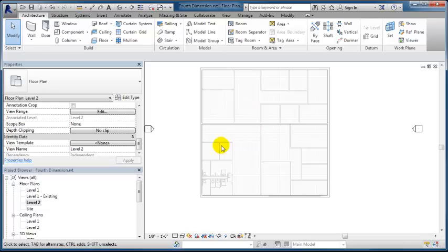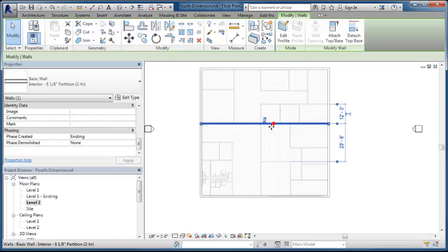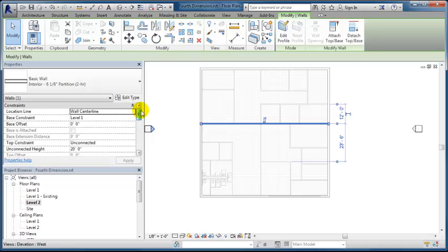All of the rest of the walls that are inside this area and this area are non-bearing walls. There are going to be all partition walls that go up 9 feet, and then our dropped ACT will be at 8 feet. So these partition walls won't even go all the way up to the roof deck. Just the one partition wall or bearing wall in the center will go all the way up to the roof. And I think I have it set up that way right now.